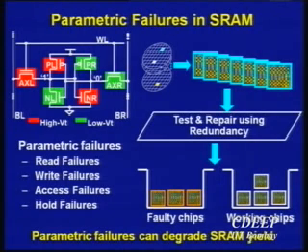The other kind of thing to look at is write failures. So write turns out is going to be different from read. When I'm reading, I don't want that 0 to go up, right? But if I'm writing into the cell, I'd like that 0 to go up, right? Because I'd like to write easily into that cell. So the conditions that I've shown here is the worst case condition for read, but it's the best case condition for write, right? So in other words, if I have a good condition for read, the write condition is going to be bad and vice versa, okay?